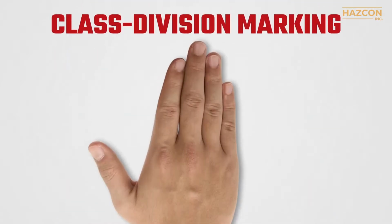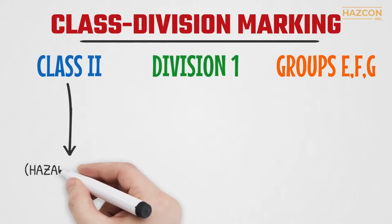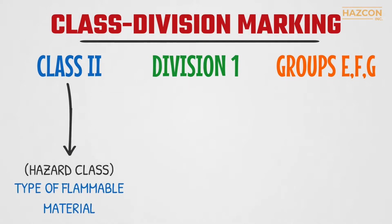A class division marking has 3 main parts, as shown in this example: Class 2, Division 1 groups E, F, G. The first part indicates the type of flammable material, Class 2, which means dusts. The second part, the division, refers to the quantities of the explosive materials present and under what conditions. It can be Division 1 or Division 2. Our example is Division 1 as was explained earlier.